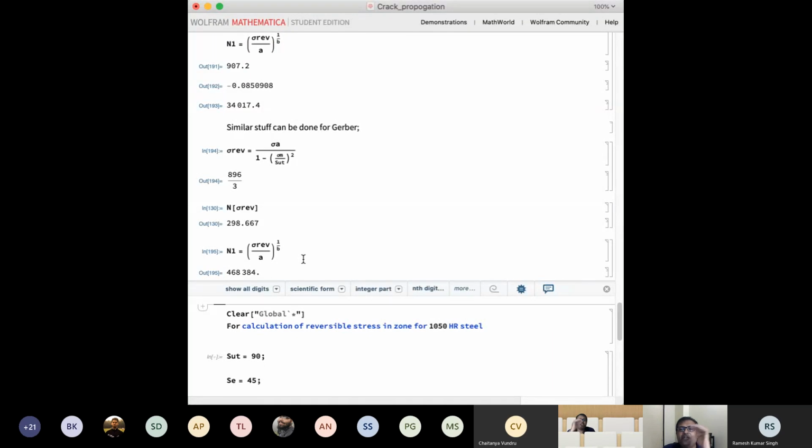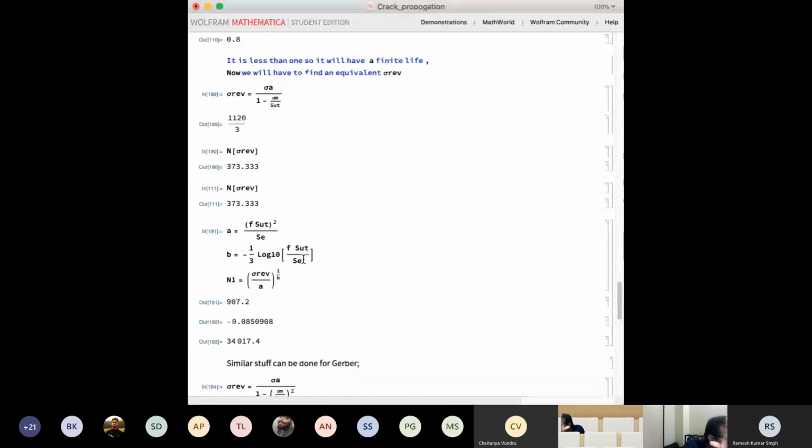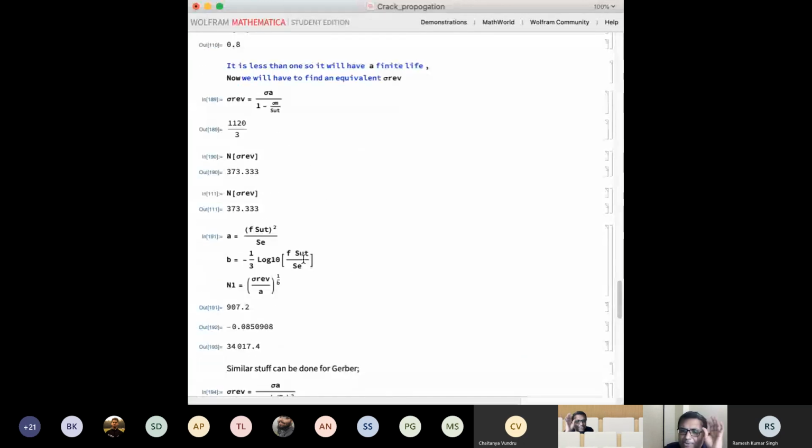Okay, that's a very good question. Why did we replace SE with sigma ref? Now what I want is, under what condition it will have infinite life. So this SE which I have gives me finite life. And I know that I have to find out what will be the value where I'll get infinite life. So if instead of my SE being 280, if my SE were 373, which we found out, then as per modified Goodman criteria, it would have infinite life.